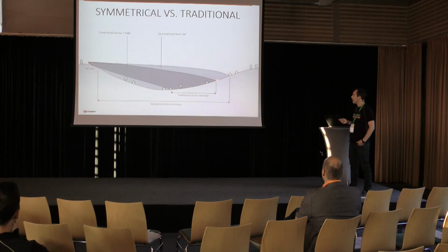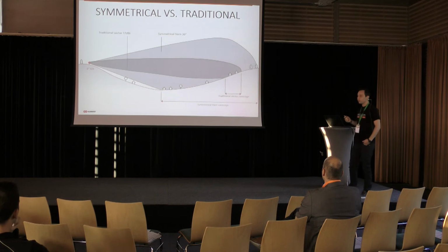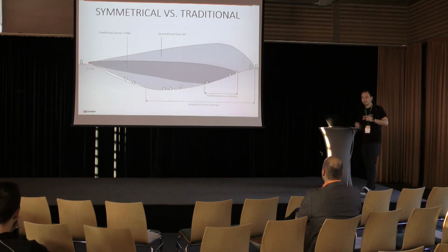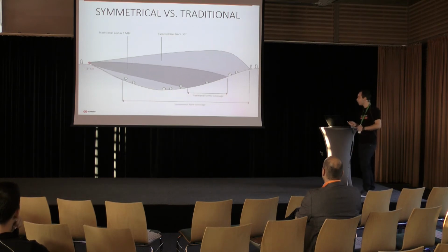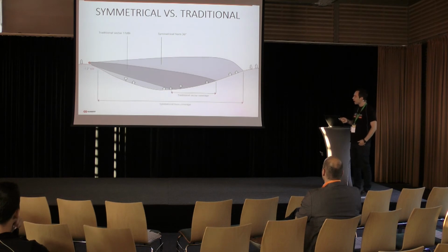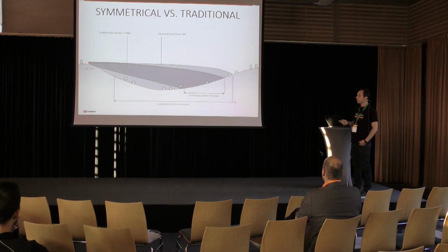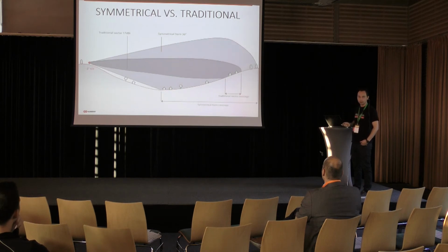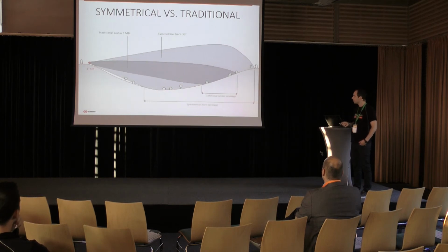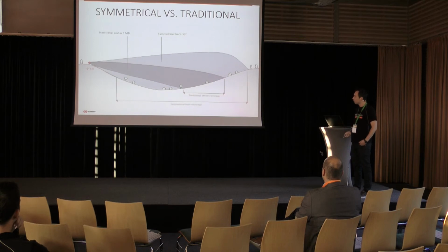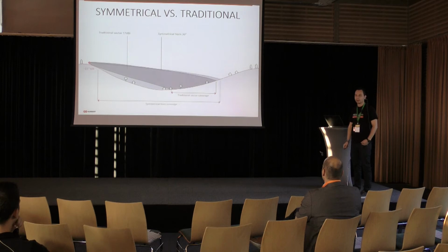But what about the other clients? Due to the shape of the beam and the same horizontal and vertical polarization on the symmetrical horn, you are able to connect all these clients with just one AP. It also matters what down tilt you make on the antenna, but now you are covering all your clients with one AP only.